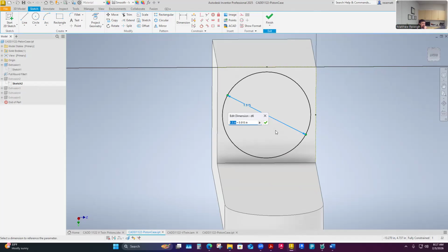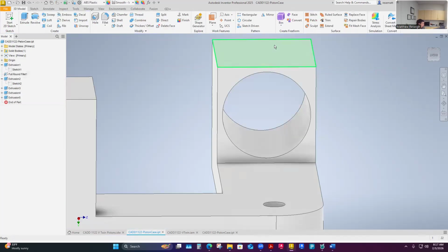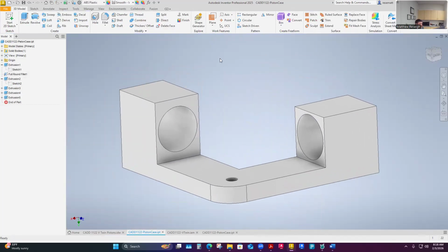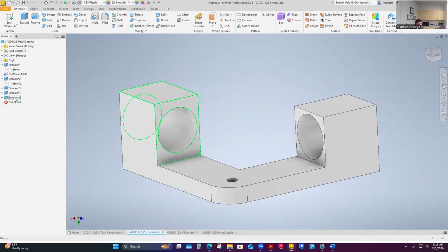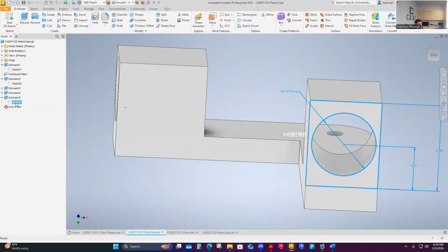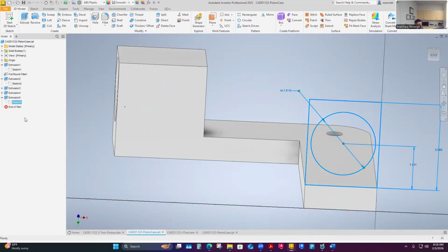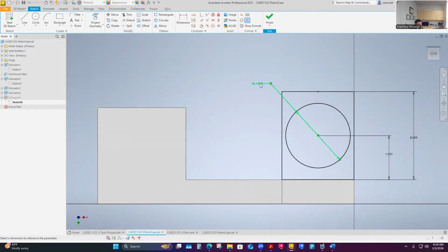Yes, and I'm gonna just make sure the other hole is the same dimension as this. So once I apply this, I'll finish this sketch. I don't know if I tied them together originally, but I can check. Like this one here is my other hole. This sketch, I think it was. If you didn't do it like I did, I'd have to go into this sketch and just make sure that this dimension is the same. I have it. It's D6.